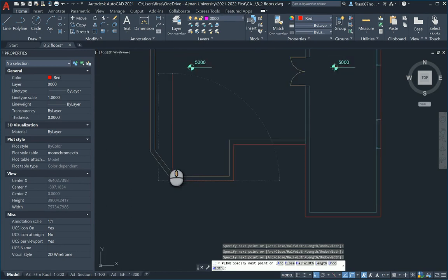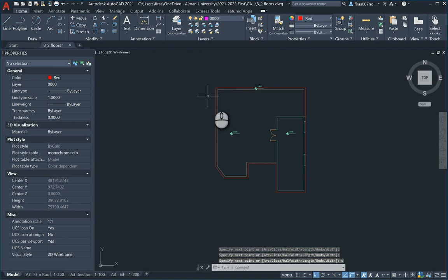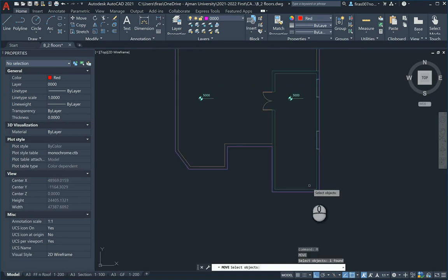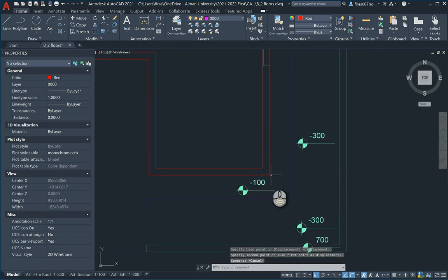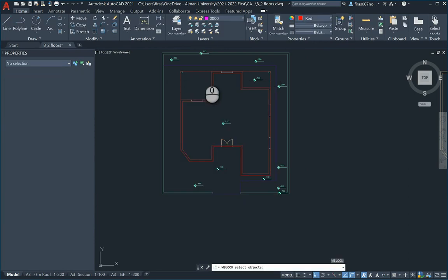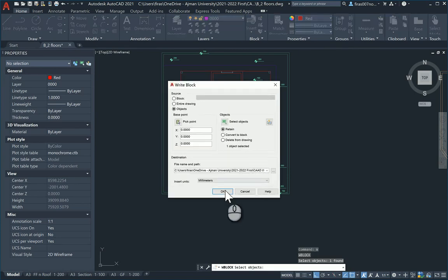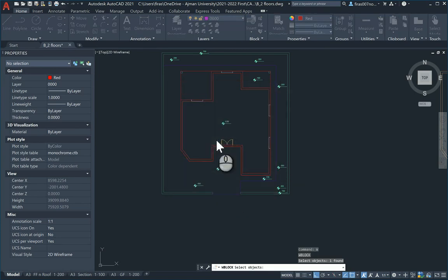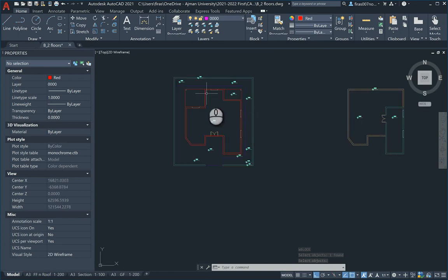Alright, you can send this as it is from its location, and then you use the 3D snapping to place it properly, or as I teach you in the class, just take a reference location, which is a common point between all the plans, and I'm using this point, this corner. Okay, right block, select, get this guy here that we have, and just say OK. I'm replacing the old one, and this is the slab, should be sitting again at 5,000 as a level, and it should be minus 200 as an extrude.